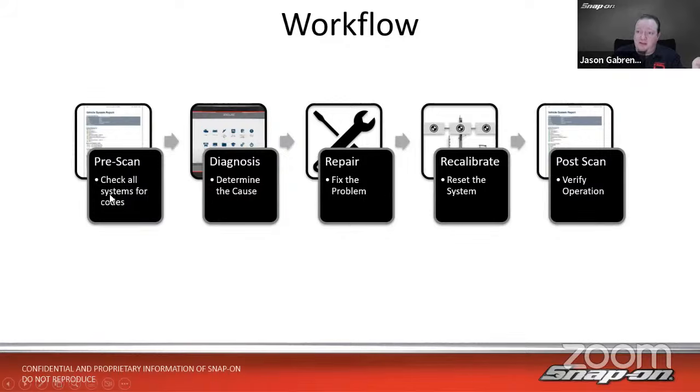Then we get to diagnosis, and that's probably where the bulk of my information retrieval will be, because I may need to go through a manufacturer's flow chart. I may need to look up wiring diagrams. I probably want to look up TSBs before I go too far. Things of that nature. Then we get into repair, fixing the problem. What do I need? How do I repair it? How do I need to go about disassembling and reassembling things? What are the torque specs?